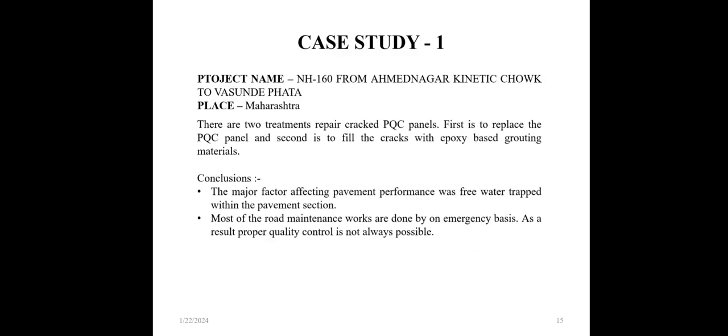Here is the case study. The project name was NH160 from Ahmednagar, Kinetic Chowk to Vasudev Path, in Maharashtra. There were two treatments to repair cracked PQC panels. First is to replace the PQC panel, and second is to fill the cracks with epoxy based grouting material.